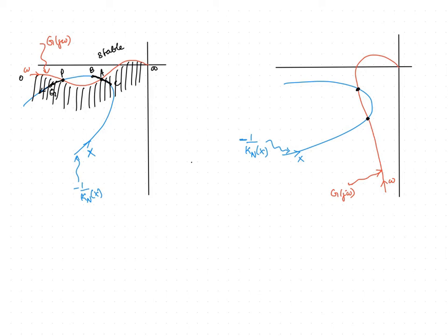It will never move back to capital P. Similarly, if the input to the nonlinearity is decreased when the system is at P, let us assume the system is moved to R. Since it is a stable region, we can see that the magnitude will still decrease. Any change from capital P will not bring the system back to P. Hence, we can say capital P is an unstable limit cycle.